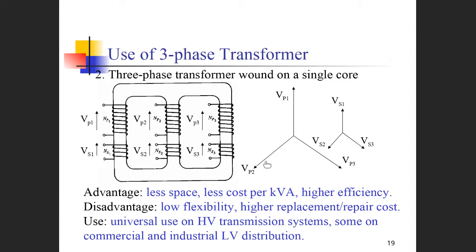Okay. Now we come to the advantages of it. Of course, in comparison with three single-phase transformers, that means the three-phase transformer bank, it uses less space, less cost per kVA, and has higher efficiency. Okay, no more explanation. The disadvantages: low flexibility, and higher replacement cost, because it is very big.